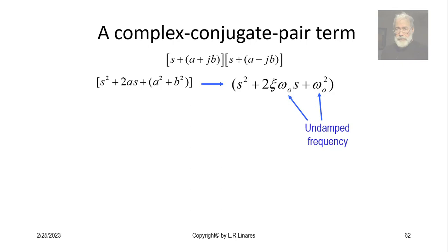By the way, that's where in the Bode plot we will have one corner in the contribution. And where's the other one? That's psi. Psi is the damping factor. So omega naught tells us where will be the corner of the contribution of that trinomial, and psi tells us how much of an overshoot we will actually get in the detailed response.